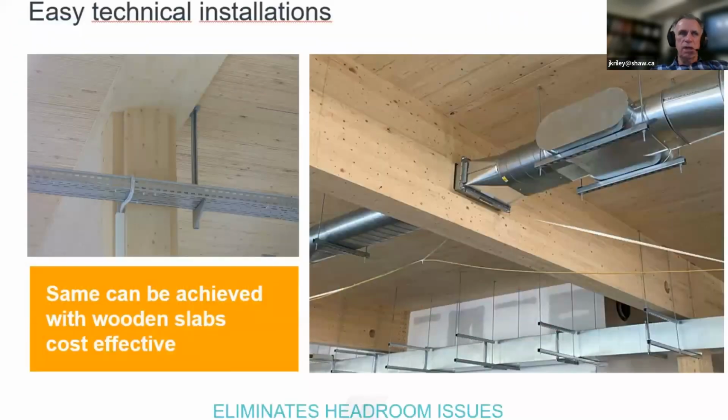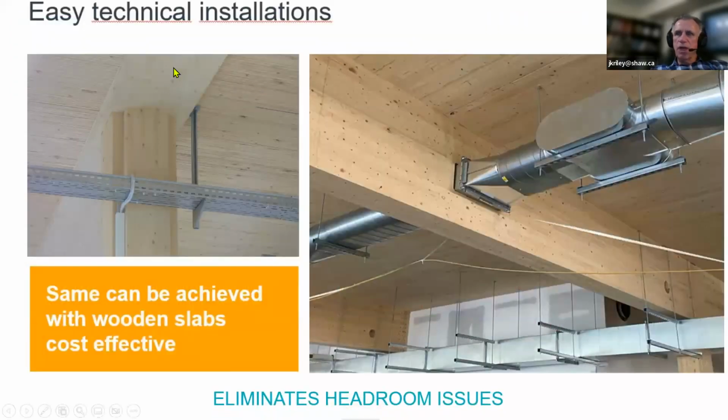So now let's have a closer look at some of the hallmarks of that. So here you see composite deck design, where the mechanical, electrical, plumbing can go wherever it needs to go. You can see the cable tray here versus this here. Now, what you don't see here is the huge expense associated with this kind of work, because this building here is a tenant improvement. Okay, so the building was originally designed to be beautiful, gorgeous, with massive drop glulam beams about a meter deep. And you can see here the tenant has had to put the HVAC system in.